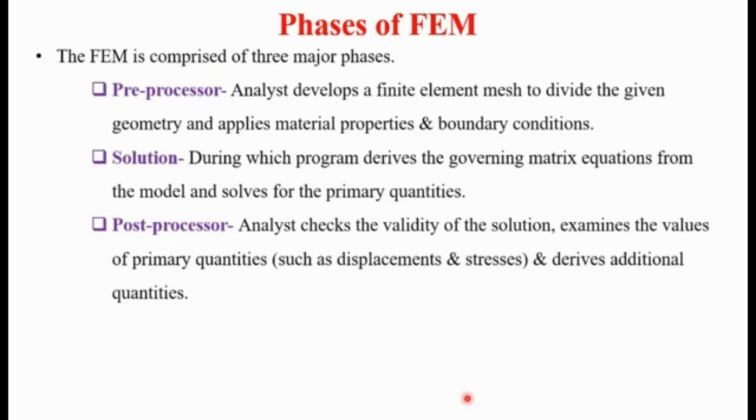Then comes the second phase of FEM, the solution phase, during which the program derives the governing matrix equations from the model and solves for the primary quantities. So after meshing all these elements, the program derives the governing matrix equations for the shape function and solves these matrix equations for the primary quantities that we need to calculate.